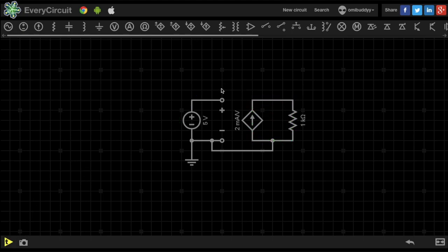So to build an amplifier, specifically a voltage amplifier, as we had a voltage as our input, we will need a voltage controlled current source or a voltage controlled voltage source. Also, we got to know that if you want to use a voltage controlled current source, we also need to adjust the output resistance so that we will get the required gain. Also, using these two building blocks, we are able to achieve zero input current from the input voltage source, which was desirable because we don't want to load the input voltage source.